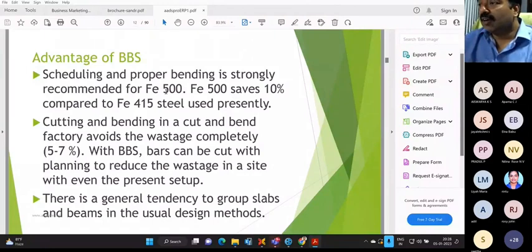We don't look at that kind of quality here. What is the usual method for breaking a bar? If you bend it twice both ways, it can break. So bending action always reduces the strength at the bend section. To avoid that reduction in strength, bars are supposed to be bent at particular diameters. That is different for 12 dia, 16 dia, 20 dia. It is all different, so we have to do it as per the code.